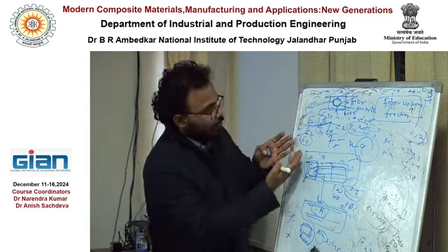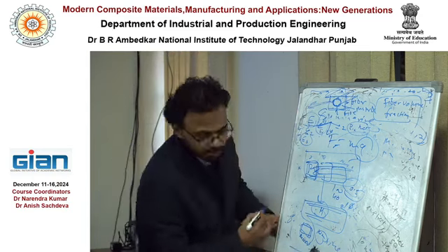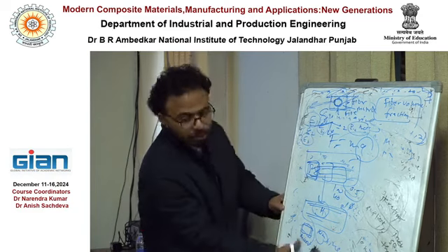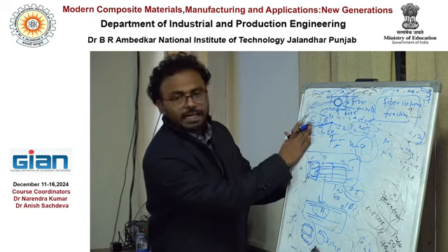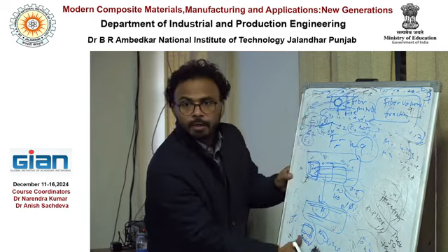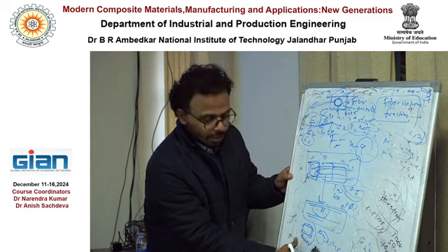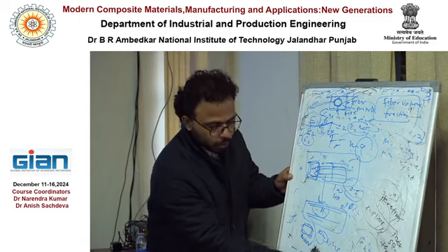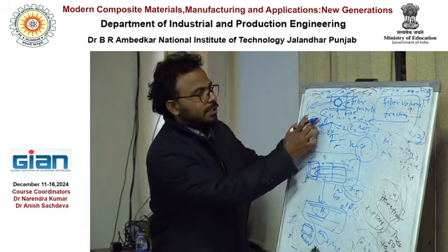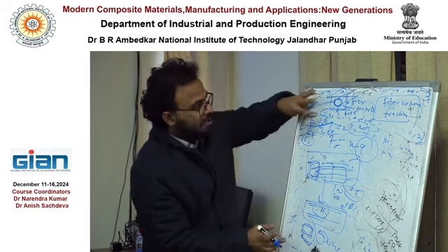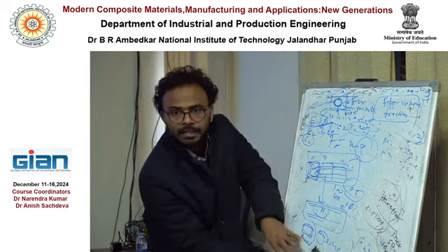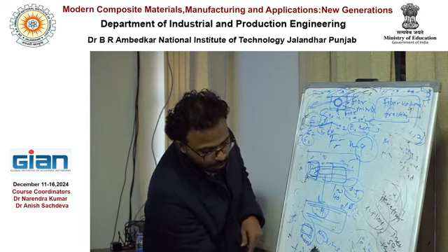Then apply to the full model. Now the full model, just make it like this only. Now apply this directly here. You got the mechanical properties from here, micromechanical. Apply this property to the continuum model directly. Now you don't need to model the ply here. You don't need to model like this now, because you created it here, right? Because this is the repetition of this, and this repetition will create this, right? So you got the properties from here. Just apply these properties here directly. Now mesh it simply, and this is the homogenized model.